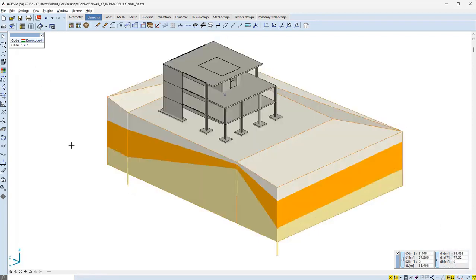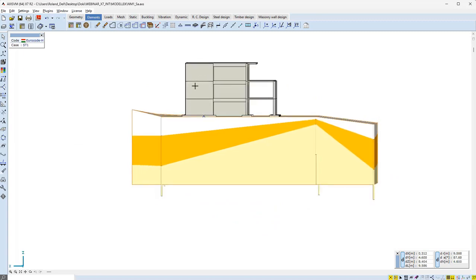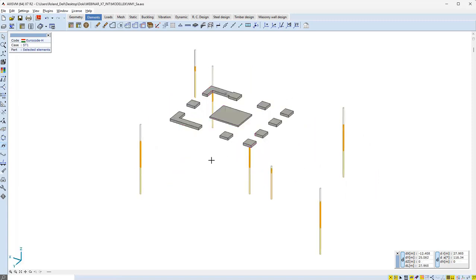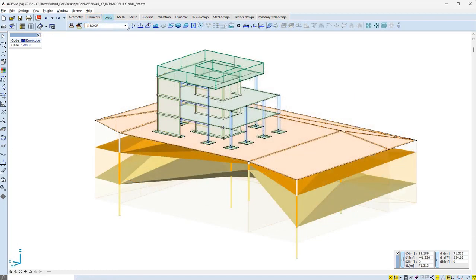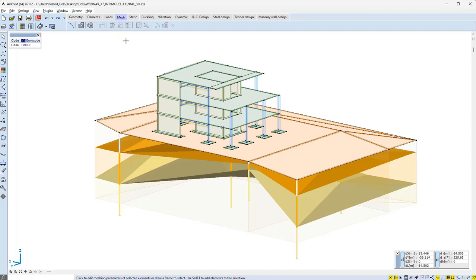As mentioned in the presentation before, working with a soil-structure coupled model requires the modeling of footings with domains of their actual sizes instead of using nodal or line supports. Contact between the footing and the soil is created automatically. This example model contains some very basic loadings like self-weight and live loads for each story. Meshing of the structure and the soil is performed separately.